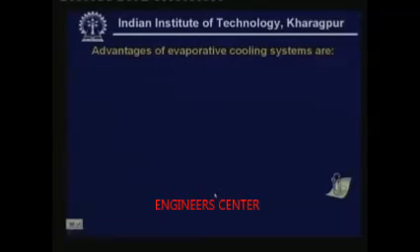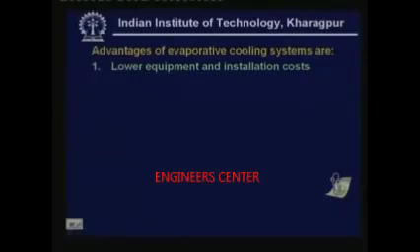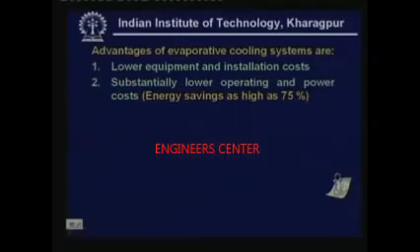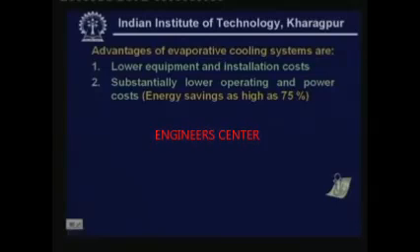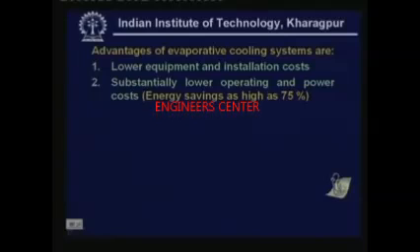Now, let us look at the advantages and disadvantages of evaporative coolers. What are the advantages? First advantage of course is that they have a lower equipment cost and installation cost compared to the conventional refrigeration system based air conditioning systems. The equipment and installation costs can be several times lower than the conventional systems. And they also have substantially lower operating and power costs because all that you require is power for running the blower and the pump. You do not have a compressor there, so the power consumption is reduced substantially, and the energy savings can be as high as 75% compared to a conventional air conditioning system. This is a major advantage of evaporative cooling systems.